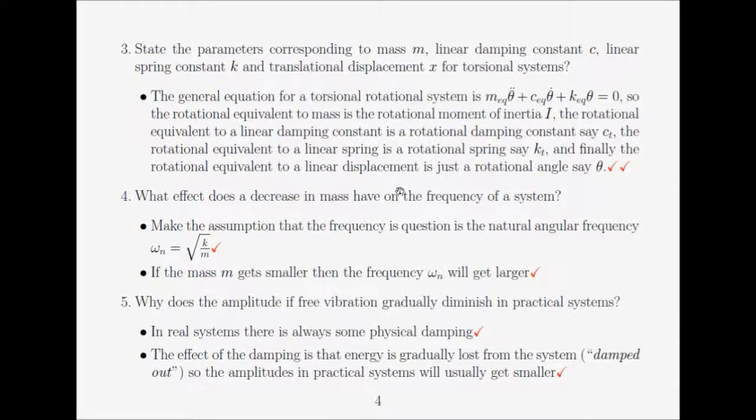The plunger, a piston inside a cylinder, a plunger system, that amount of energy physically moves the damper into the oil, and that kinetic energy is transferred into mechanical energy, and that mechanical energy disturbs the oil inside the damper, and that basically takes the energy. So the kinetic energy is converted into mechanical energy, which is then converted into heat energy, and the heat energy is basically lost, goes into the oil, and that energy comes out of the system.